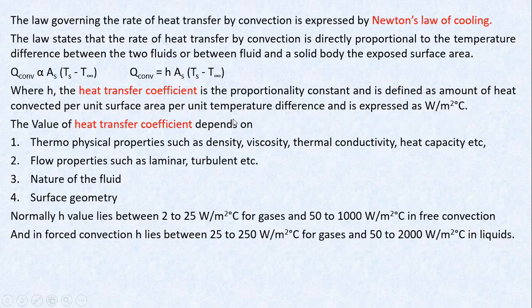The value of the heat transfer coefficient depends on many factors: thermophysical properties, mainly density, viscosity, thermal conductivity, and heat capacity. It also depends on the flow properties, whether the flow is laminar or turbulent. It depends on the nature of the fluid and also the surface geometry, such as surface roughness, smoothness, etc.